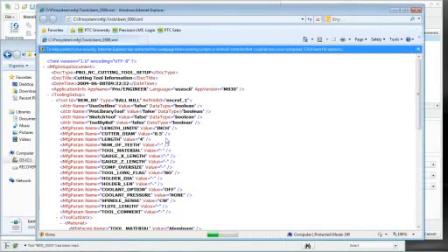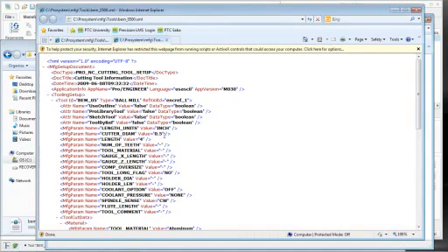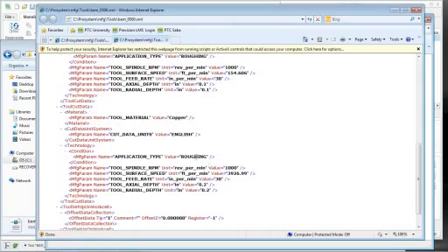All right, so what you see in the .xml file is general information. You talk about the length, the cutter diameter, but what you see here is the tool material, what is the application, and the information for speed, feed, and depth of cut. And then a little bit lower is copper, the application, and the values for speed and feed. And again, as I save that, all it does is continue to append this .xml file. And so all that information is stored into that spot, and then from that point it is pushed or can be pushed into your parameters.